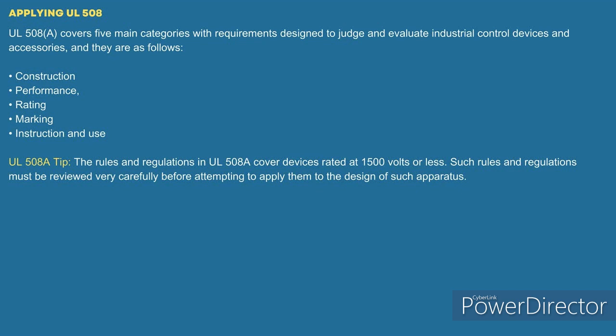Then they said it was inside at the AC equipment. I said, is that rated for a wet location? And they said, what the hell's that got to do with it? I said, well, you're trying to take an NEC requirement and place it inside that equipment. You don't have any NEC rules that I'm aware of, especially when you look at 90.7, that apply to the inside of that equipment.